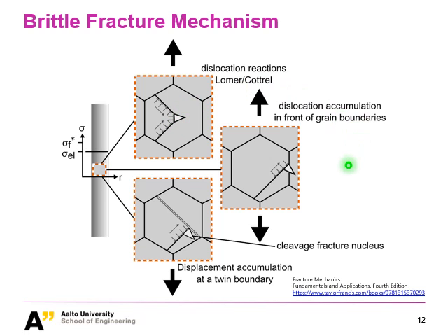The second point is the typical grain boundaries, because that is a place with a lot of dislocations that are not that organized. That is a place where dislocations always get stuck and accumulate because they cannot move easily, since the slip system changes. When dislocations accumulate a lot, you can imagine that will develop into a crack initiation.